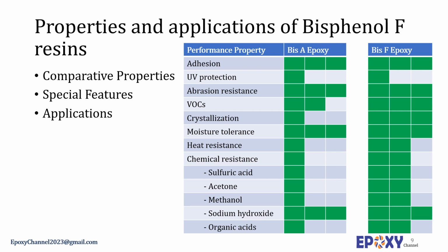Epoxy resins based on Bisphenol F are used primarily as functional diluents in applications requiring a low viscosity, high-performance resin systems, for example, solvent-free coatings. Higher filler levels and faster bubble release are possible because of the lower viscosities. The higher epoxy content and functionality of Bisphenol-F epoxy resins provide improved chemical resistance compared to conventional Bisphenol A epoxies.